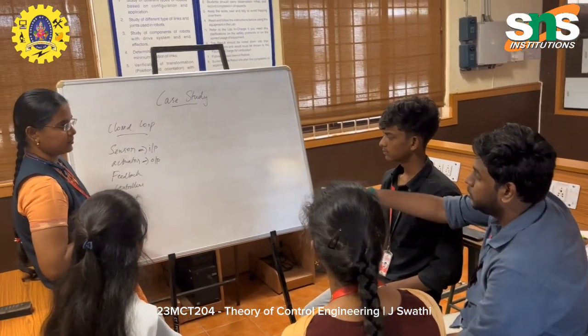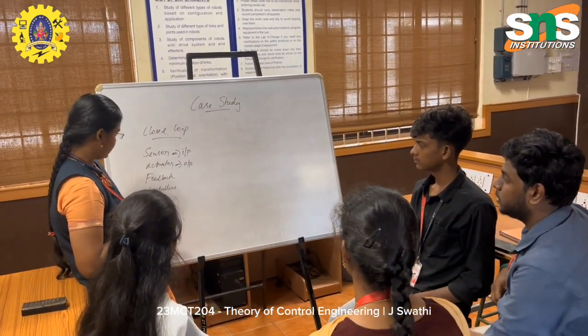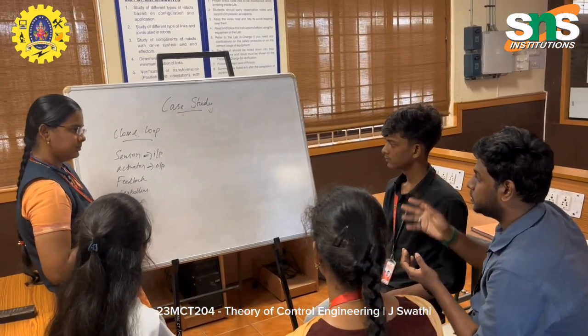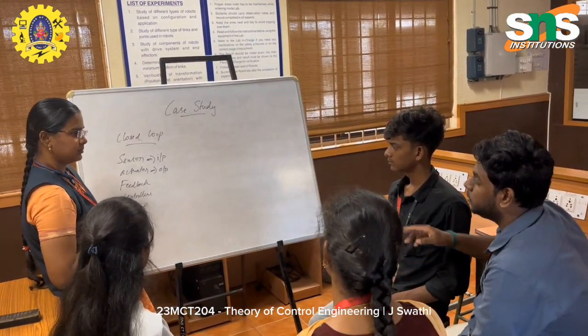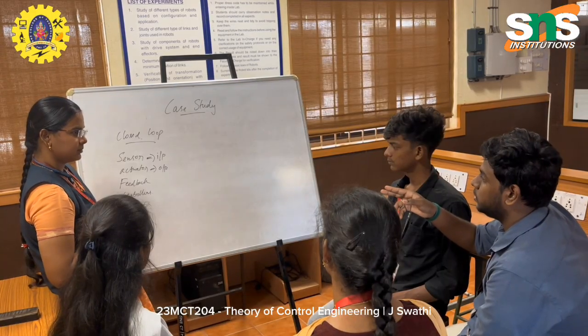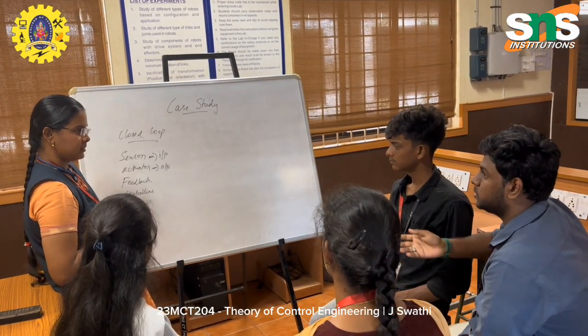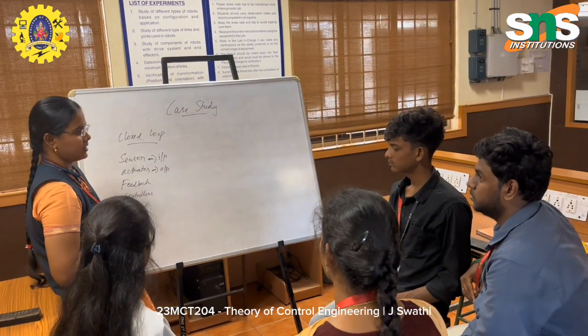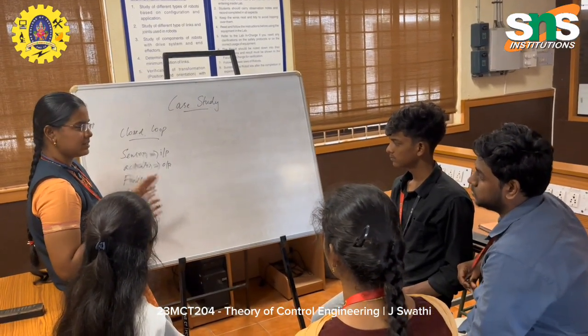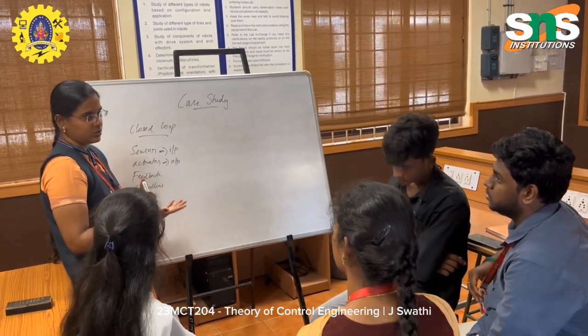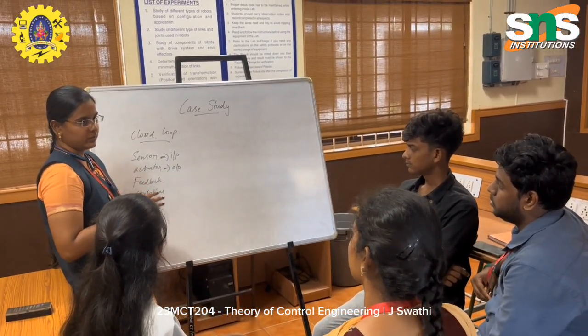By using the supporting system like feedback and controller, we can compare the input. If the preset values and the input are similar, we can pass the signals to output, and it will maintain the soil temperature or moisture. Very good. So the basic thing is I have to maintain my soil components, like temperature, humidity, moisture.